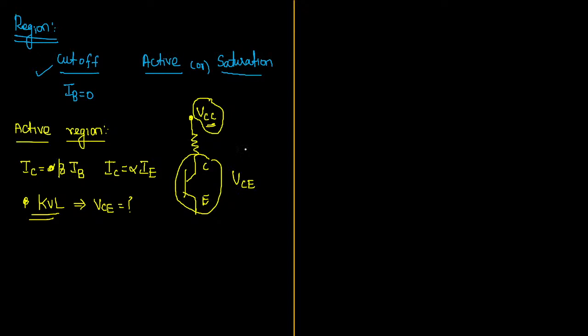Okay sir. Here the value of collector to emitter voltage in saturation region is less than or equal to 0.2 volts. Mostly it will be 0.2 volts only. So the collector to emitter saturation voltage will be 0.2. You can fix this value as 0.2. Okay sir, so I fixed the saturation voltage as 0.2. Now you compare the collector to emitter voltage.